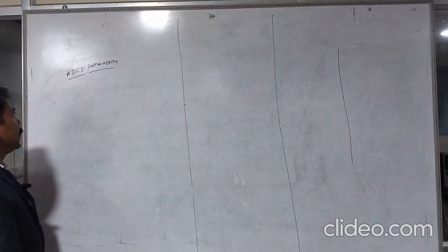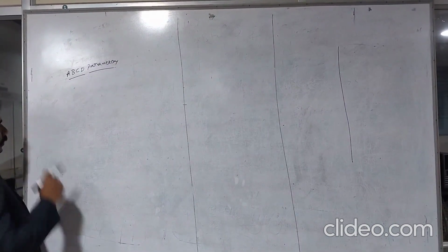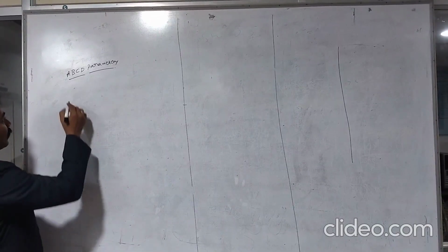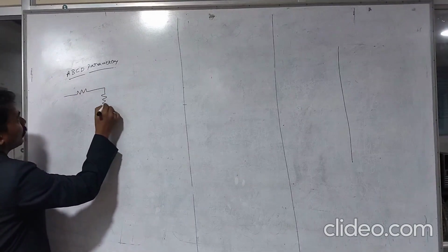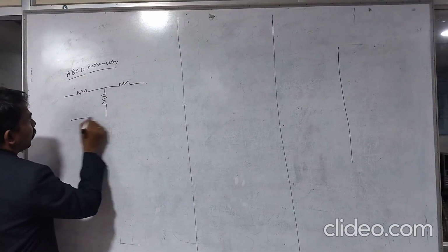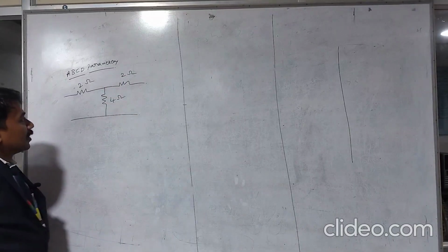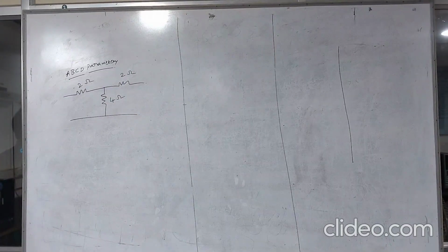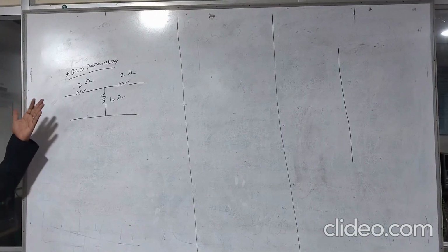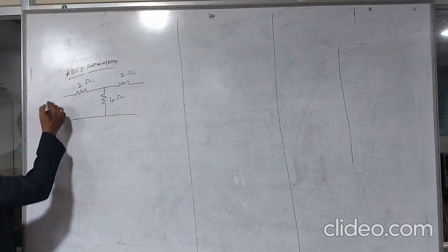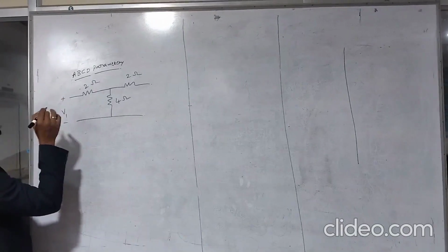ABCD parameters are T parameters. Okay. So now we are going to determine the corresponding ABCD parameters of the following two-port network. So again, it belongs to a T-type network. For a T-type network, apply KVL equations irrespective of the required parameters, either ABCD parameters or H, whatever it may be. In the case of a T network, the most convenient thing is Z parameters, but still to determine ABCD parameters also, you can do the conversion. You need not remember any kind of formulas here.